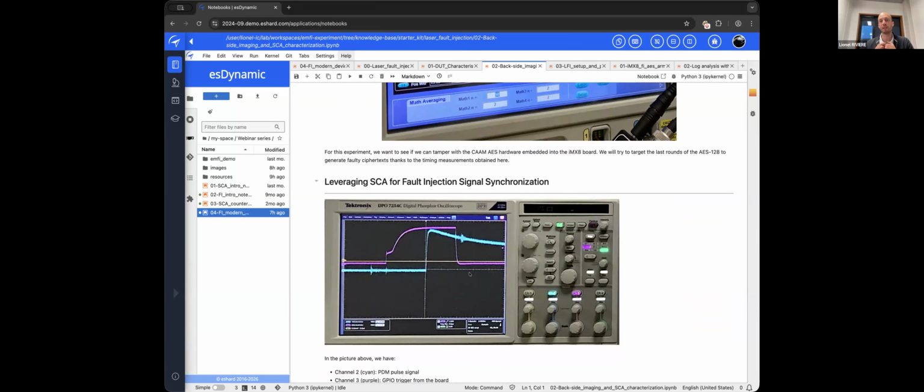My goal, from this AES that I want to attack, would be to perform a DFA, a differential fault attack. If I use the Piret and Quisquater technique, I will need to focus towards the end, on the last 2 rounds in which I want to tamper with the encryption. So I can also reduce the time frame during which I will do the fault injection.